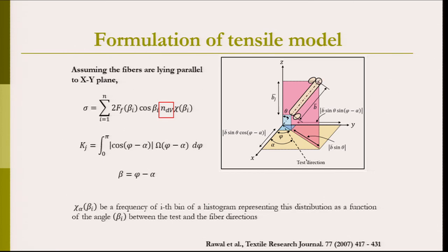So, there is a fiber being connected by two successive contacts, and again we make use of the meso domain, we try to calculate the total stress, which is denoted here by sigma, and here we try to calculate the tensile characteristics, let us say for a thermally bonded non-woven material, where all the fibers are completely fused with each other, and the fiber to fiber contact is presumably a stronger contact in case of thermally bonded non-woven.